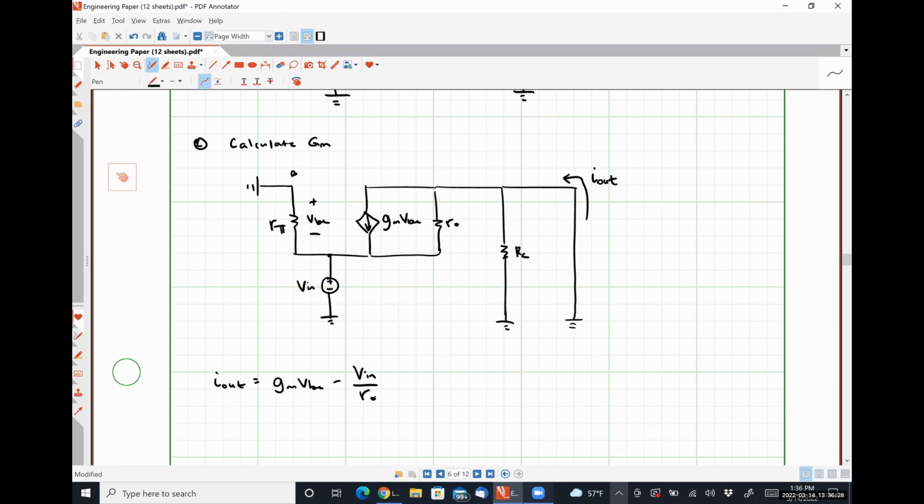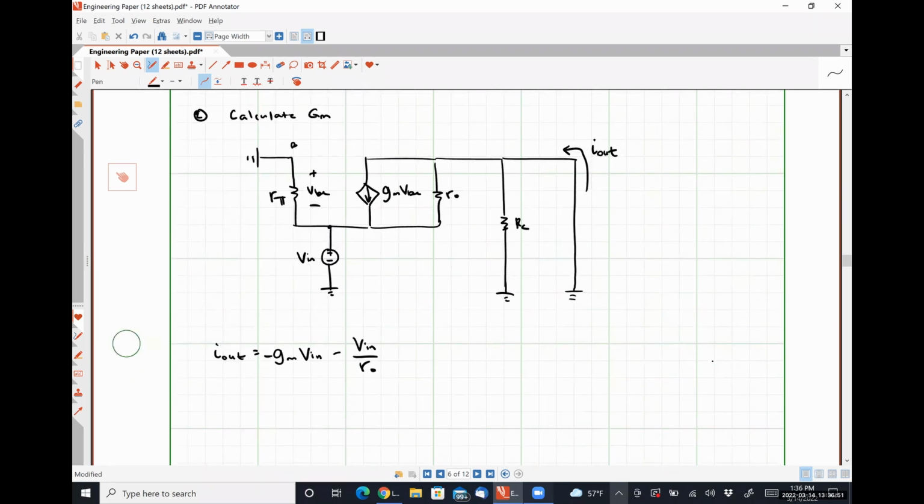So they're the same voltage because they're the voltage measured between this point and ground. So this point and ground and this point and ground are the same thing, but they have the opposite polarities. VBE is negative VN. So what I'm going to do is replace this VBE with a VN like here and put a negative sign there. Are we okay with this? Therefore, capital GM is simply negative GM plus 1 over R naught. Are we okay with that?